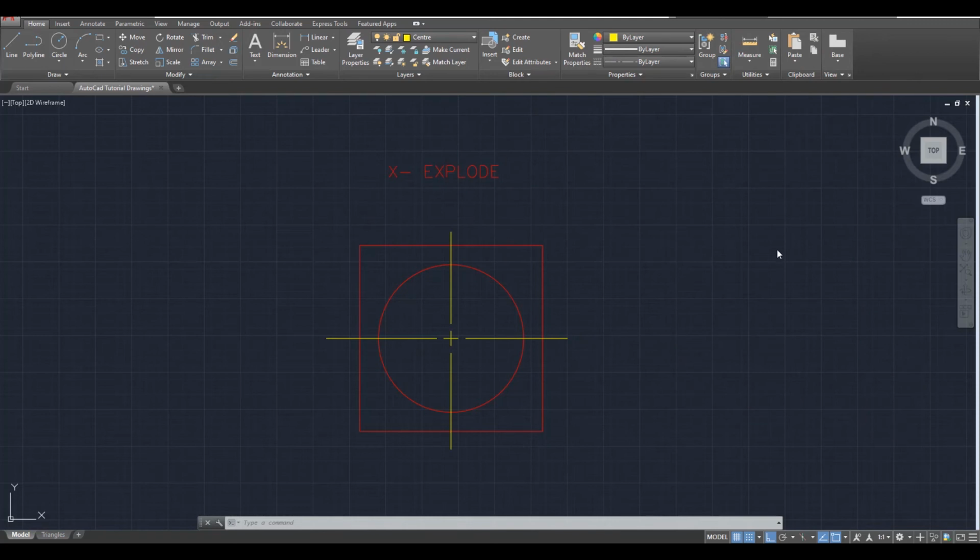We're talking about explode, wherein you have a geometrical shape such as a square, and you can see that a square is just 4 sides or 4 line segments. However, if you use the polygon tool and draw a square, you'll just have one solid shape. But suppose you want to turn this into 4 line segments. Well, never fear, because the explode command is here.